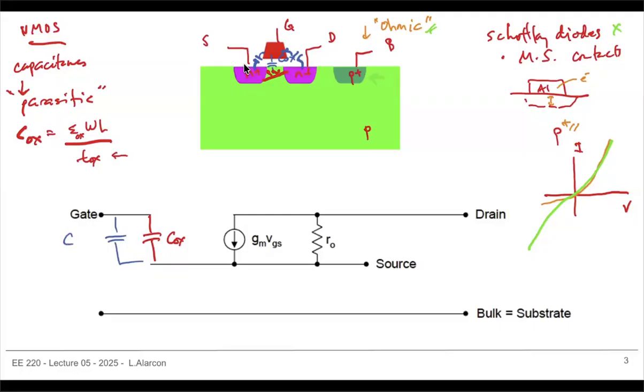So this is the overlap capacitance between gate and source. And you have a gate to drain capacitance. Okay. This overlap, let's just call that CGD. Right. And for CGS, that is the sum of the overlap and COX. Right. That's a total, this plus, yeah.